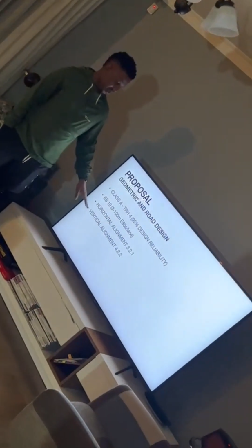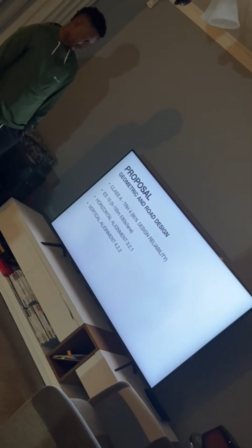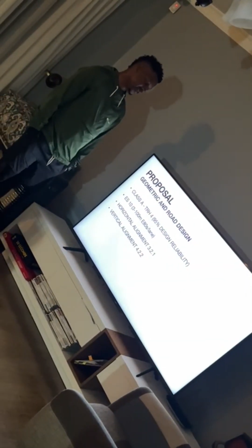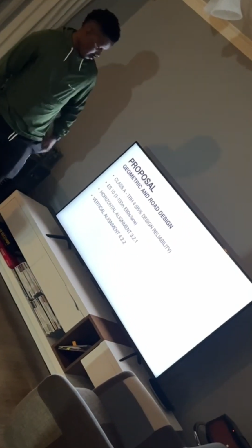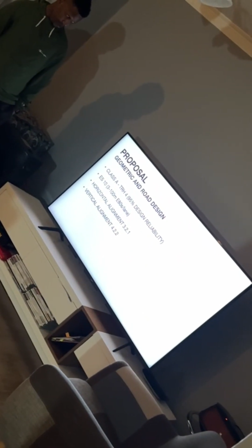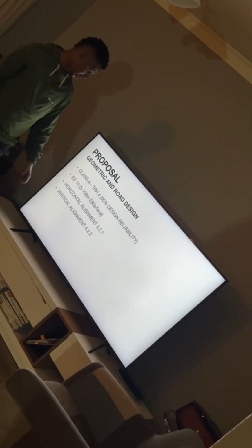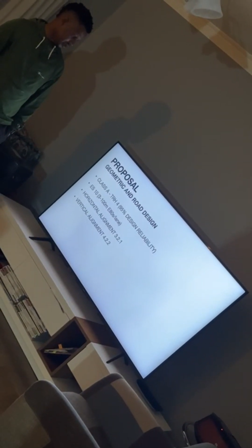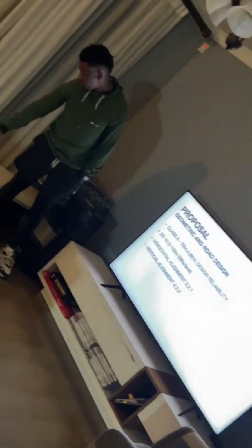In terms of the horizontal alignment, table 3.2.1, for the design speed of 80 kilometers per hour, we need to have our radius at 140 meters for that to be compliant. Vertical alignment for operating speed of 80 kilometers per hour. This is for the horizontal alignment, that is 210 meters radius. For the vertical alignment, that's 140 meters as well, the length of curve, for it to be a safe road.